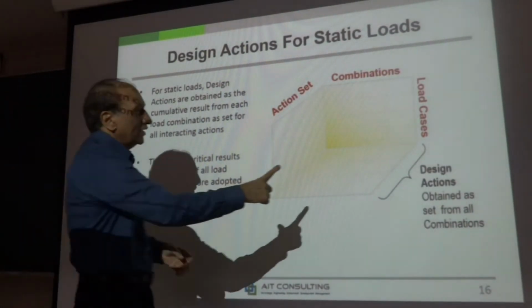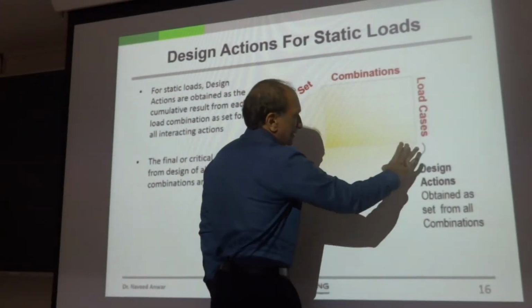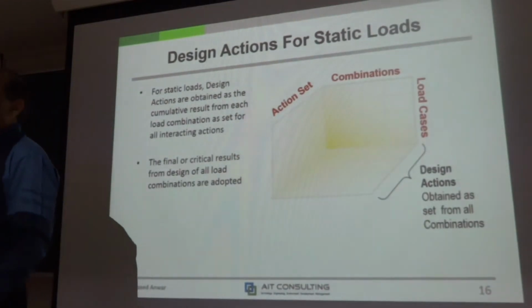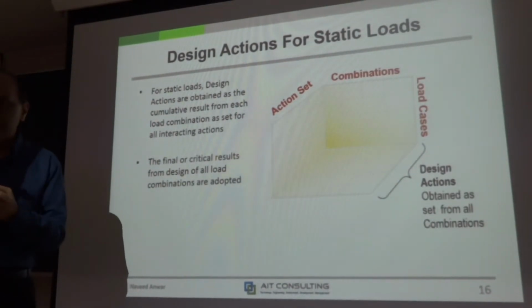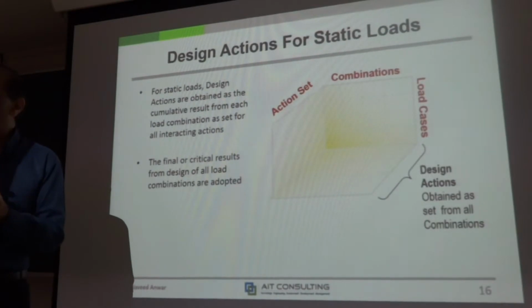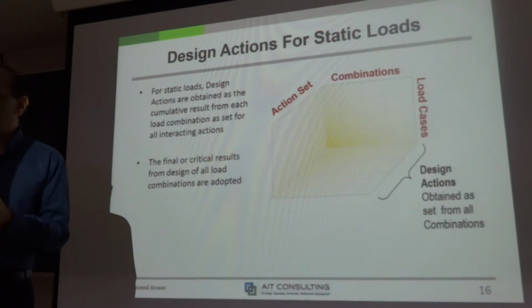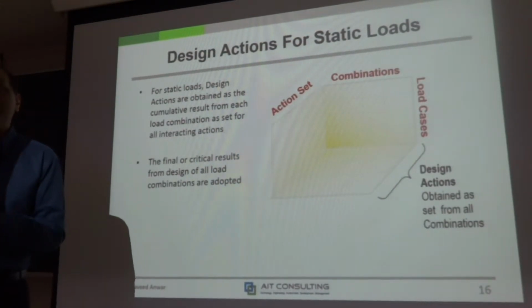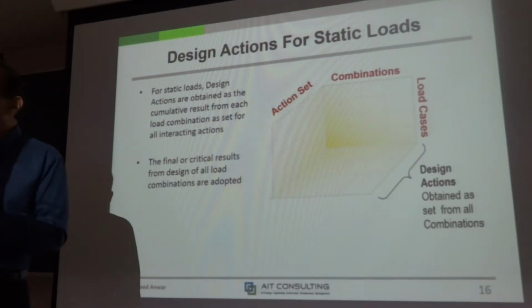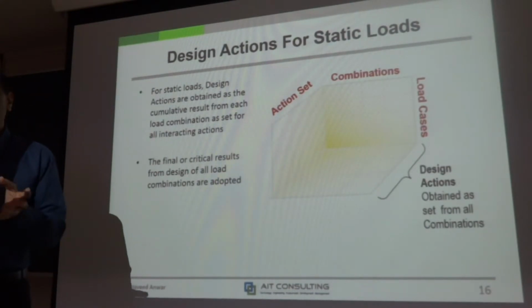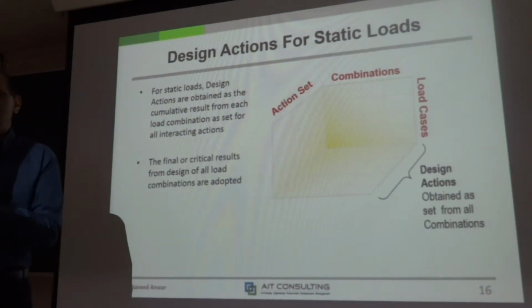Right? So 3 items together form a set. They cannot be separated. They must be taken as a set all the time. Axial load, moment X, moment Y for the design of columns together; for the beam, bending moment, shear and torsion together; and for slab, MX and MY and MXY together, and so on. So every time we normally have 3 or 4 actions that must be designed together, not independently. So envelope cannot be used.